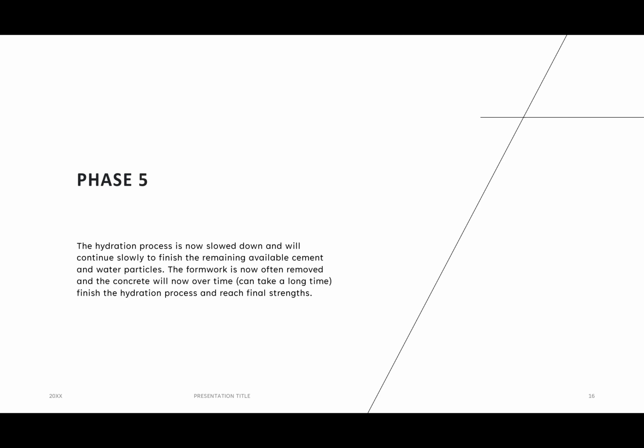So the last phase, the diffusion period. The hydration process is now slowed down and will continue slowing to finish the remaining available cement and water particles. The formwork is now often removed, and the concrete will, over time, finish the hydration process and reach final strengths.